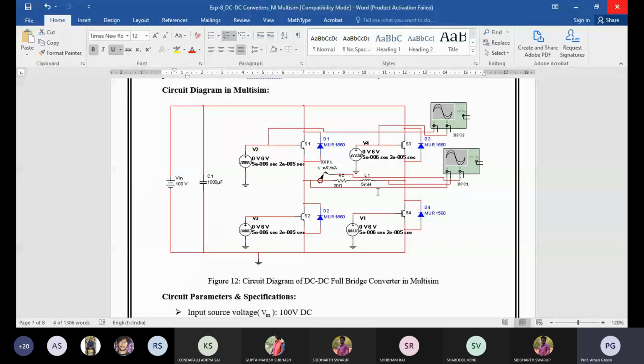So duty we can also calculate. How to calculate the duty? We should get the output voltage here. On here you can see the current probe. The current probe rating is 1 millivolt per milliampere. Here you can also find out the output voltage. If you have the output voltage, then for the turn on condition, how do we get that average value, V average?